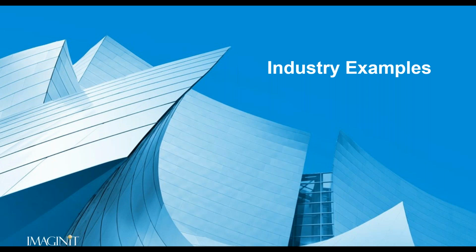If we're doing interiors or exteriors of buildings, a laser scanner might be better. Again, you can do them with photogrammetry, no problem. It's just going to take a lot more data and a lot more processing. Okay? Again, the way you take the photos is also important. You can't just walk into a room, or go around an object, and randomly take photos wherever you want. There is a specific method for taking photos, which becomes more important when we're looking at photogrammetry instead of using laser scanners.